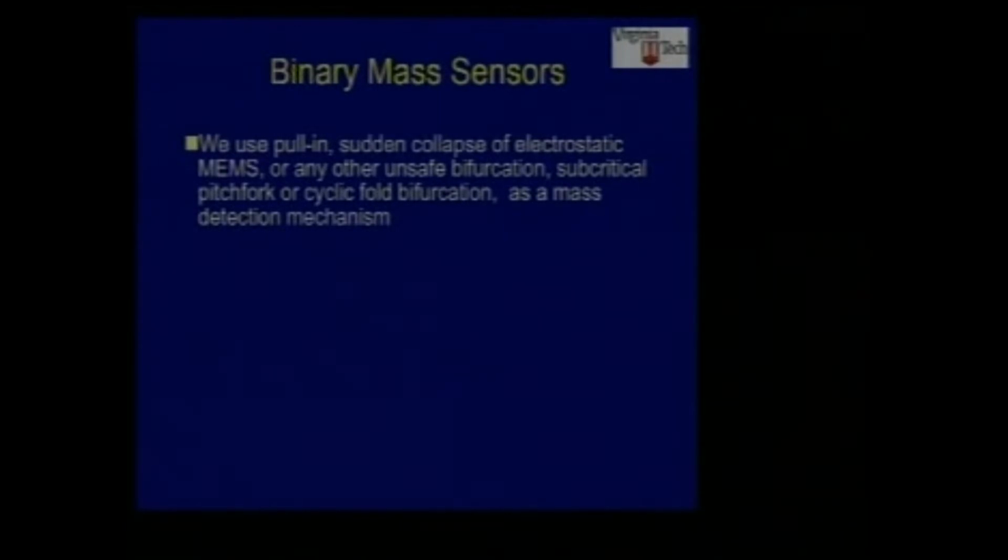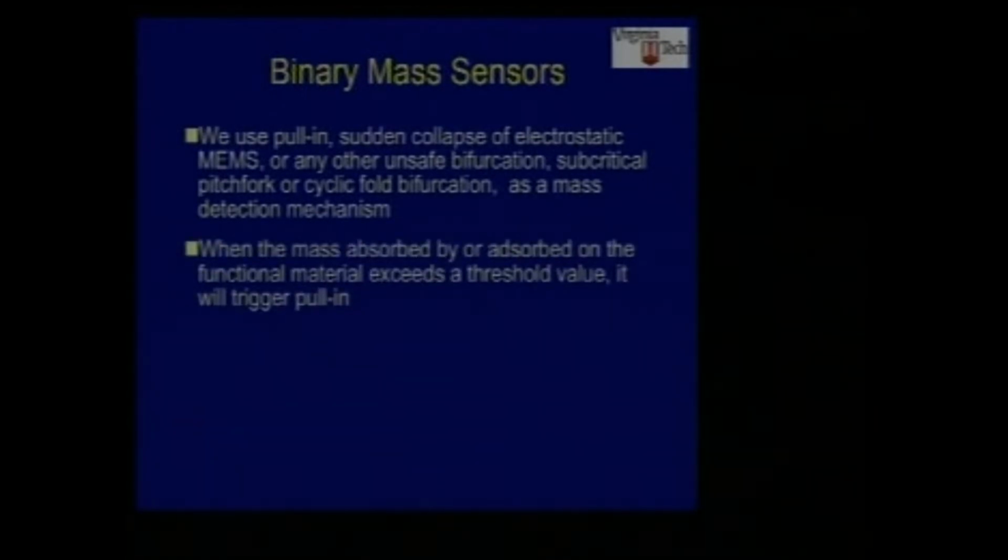On the other hand, you have now what I'm calling the binary, the threshold, yes or no, which I mentioned there. One of the major things which you say there is a sudden change in the system. And the sudden change could be with the pull-in instability, where you have systems which are electrostatically actuated, say, a beam or a plate, a membrane, and that will be the threshold which you want to use. And I'll explain some of that there.